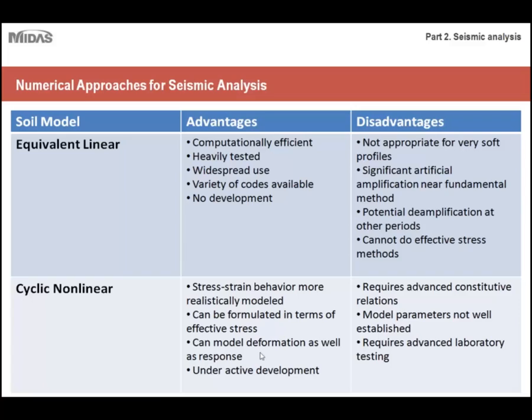So that's another key factor, that it can take deformation of soil into account as well as failure. And it's under active development. That's one of the key advantages of it, that there are still scientists who are working on developing cyclic nonlinear analysis to be more widely used, or to be more efficiently used. So the disadvantages of cyclic nonlinear modeling is it requires advanced constitutive relations.